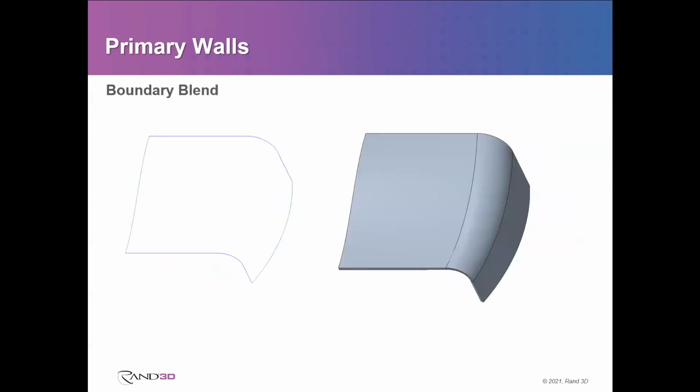And then you also could potentially do a boundary blend. A boundary blend is where you would have to lay out curves that give you the shape of what you want to create. They've got curves in two directions here. There are the two green curves that define the left to right contour, and the two blue curves here, that's the front to back. It's going to blend in both directions to create the Sheetmetal wall.